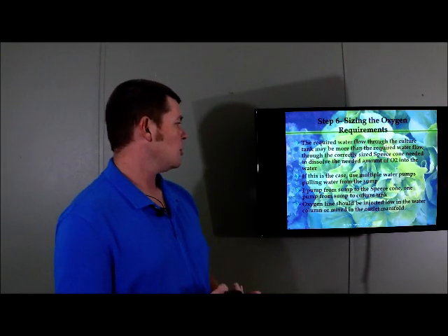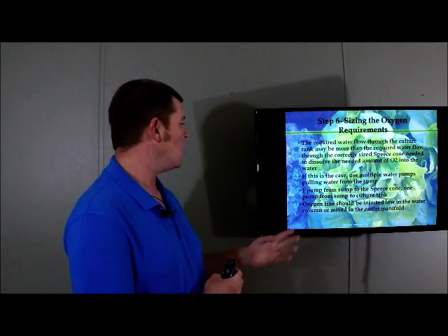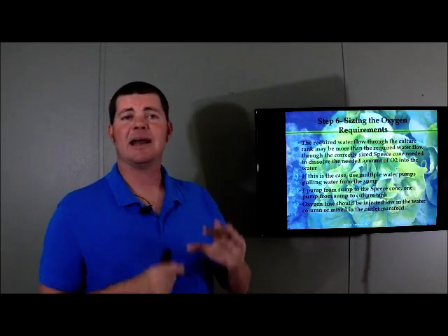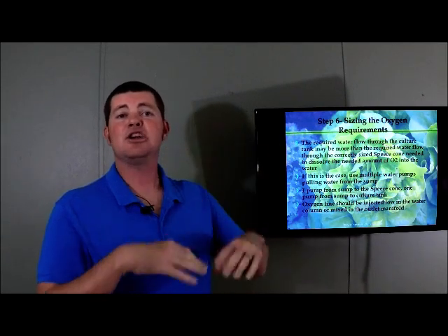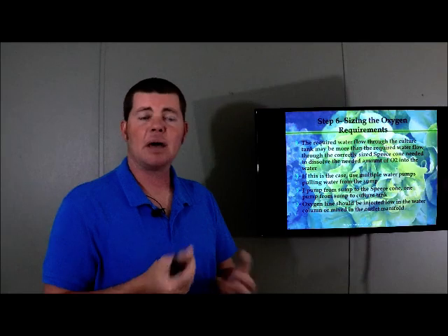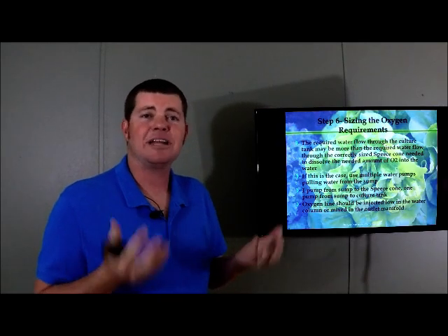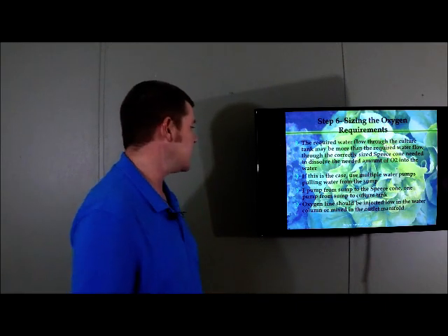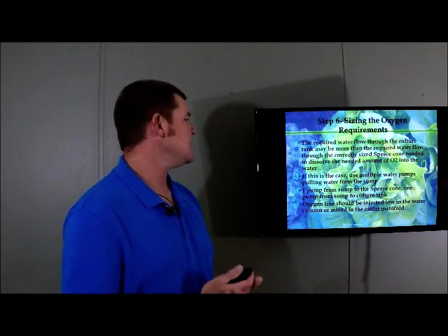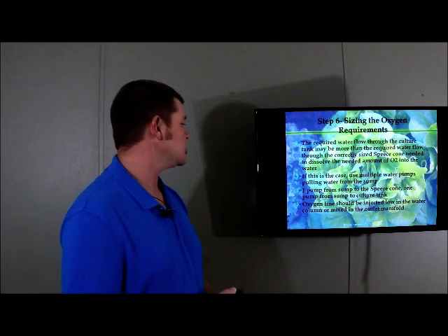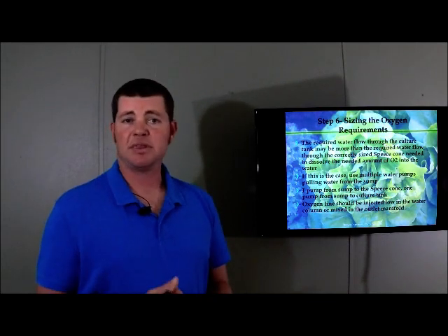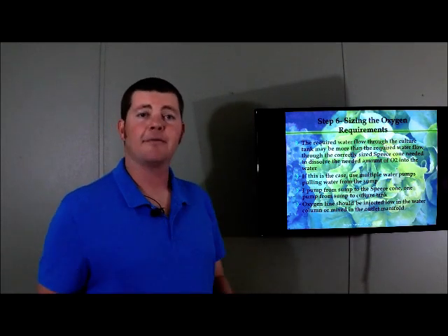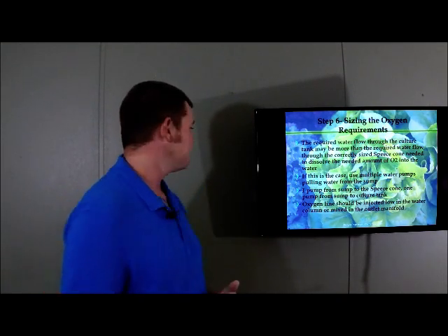Oxygen lines should be injected either as a separate line low into the water column so that it's not right by the top and you don't get all your high oxygen water near the surface where it might come out and transfuse into the air around, okay? So you want to inject it low into the culture tank. Or that line can be plumbed in with the main recirculation line and mixed within the outlet manifold and delivered into the tank within one outlet manifold, okay? It can be mixed into that main line.